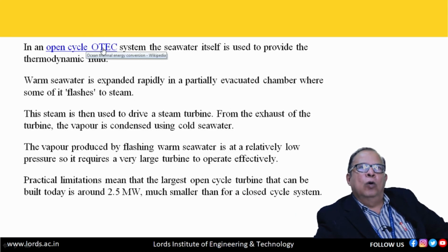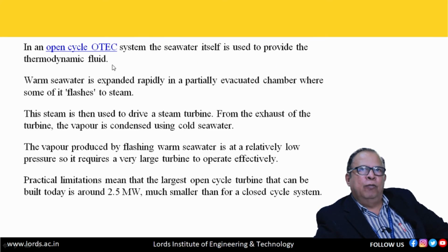Then in an open cycle OTEC system, the seawater itself is used to provide the thermodynamic fluid. As I told you, seawater itself is used as a working fluid. That is, warm seawater is expanded rapidly in a partially evacuated chamber where some of it flashes to steam. That means part of that water flashes into steam. This steam is then used to drive a steam turbine. From the exhaust of the turbine, the vapor is condensed using cold seawater.